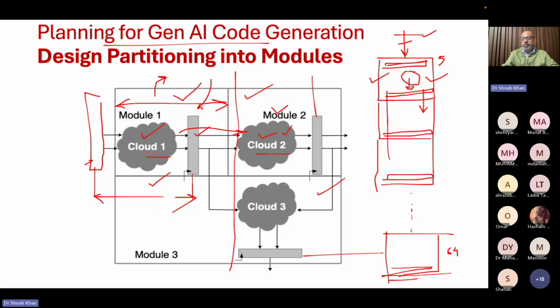Otherwise, there is no point in replicating it 64 times, because if the next value requires the output of one block, you have to wait. You cannot put in the new block unless you spend all these 64 times. This block works, then it is sitting idle, passing the result to the next block. That block works, then passes it on and is idle. So at any time, out of 64 blocks, only one block is working, because you need the result of the 64th iteration to start the 65th iteration on a new block. So it does not make any sense.